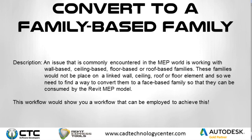And today we'll be talking about an issue that is encountered on the MEP side of the world, particularly with regard to families. On the MEP side, what we typically do is link a project file in. This could be an architecture model or a structure model, and we need to place our MEP family. This could be a panel board or a light fixture or a diffuser, and these families need to be face based in order to host to the different faces of the linked model.